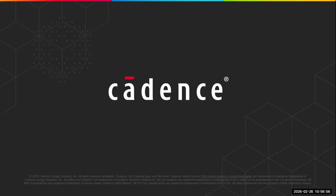There's one comment: if I use a public AI tool to generate RTL, can I port that to Cadence tools? There's a whole set of tools that I didn't discuss that take the RTL and implement it: logic synthesis tools, place and route tools. Those logic synthesis tools can take RTL from any source. Whether you hand created it, created it with Stratus, or created it with a public AI tool, it doesn't matter. They ingest RTL.